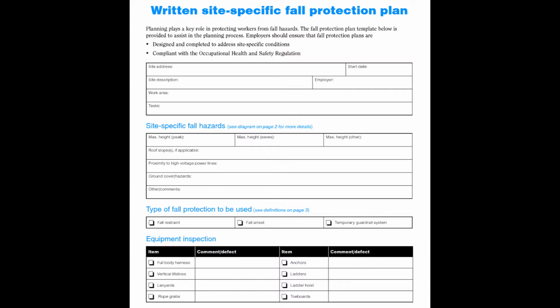Where no other alternative measure has been implemented, the employer shall implement a safety monitoring system in conformance with 1926.502. The fall protection plan must include a statement which provides a name or other method of identification for each employee who is designated to work in controlled access zones. No other employees may enter controlled access zones. In the event an employee falls or some other related serious incident occurs, for example a near miss, Plaas Incorporated shall investigate the circumstances of the fall or other incident to determine if the fall protection plan needs to be changed, for example new practices, procedures, or training, and shall implement those changes to prevent similar types of falls or incidents.